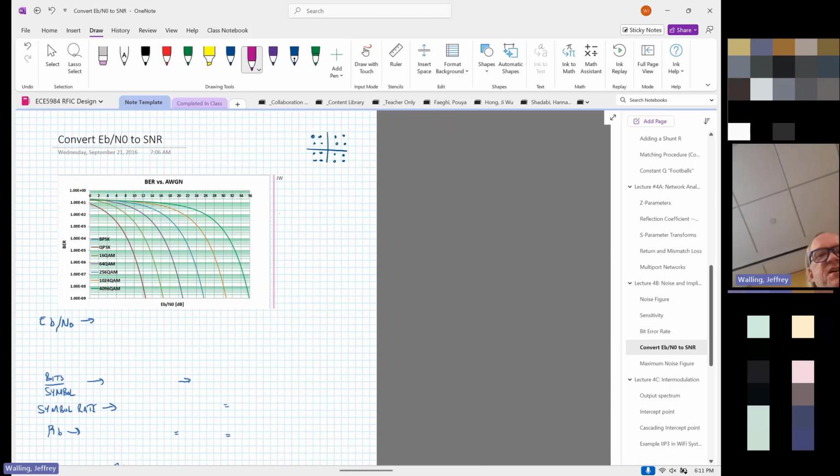So, for instance, if I have a bit that's supposed to be at this point, but because of noise its uncertainty region is much bigger, it can land anywhere in that red circle I've just drawn. I want to make sure that my system is spec'd such that I don't mistake anywhere in that red circle to be one of these other particular bits.